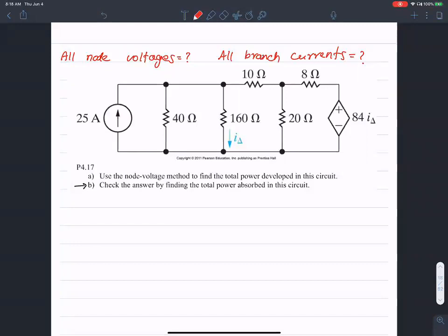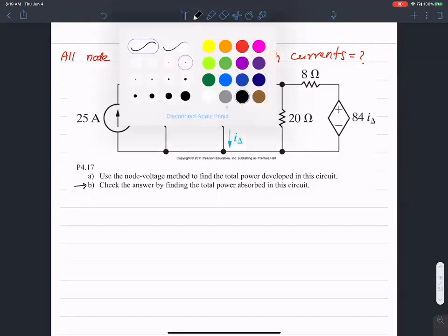To get started with this problem. Okay, do you want to get us started, Darius? Yes, I want to make sure that I was setting this up right because I want to start with the whole loop. I want to go all the way around, making the current going out from each node I1, I2, I3, respectively. Sure. So do you want to pick a reference node?